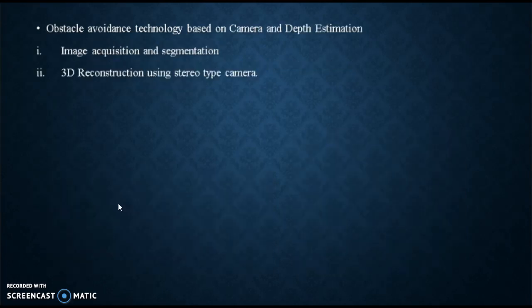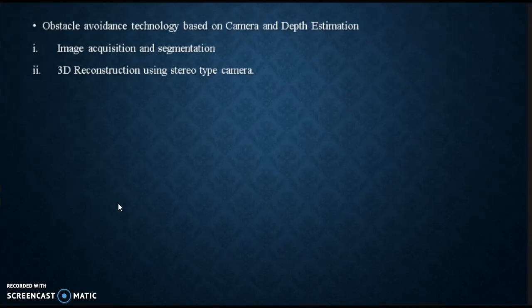And then the second sensor we have used in this wheel type mobile robot is the cameras. According to the pinhole camera model, the acquisition module encapsulates all the intrinsic parameters of the cameras and the function to obtain distorted stereo images. The system does not rectify the image, and thus it does not need the extrinsic parameters of the stereo rig.